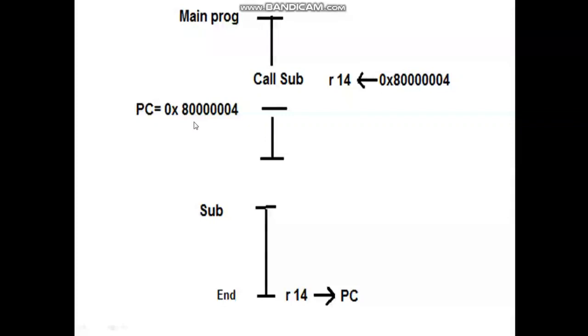You know, when an address is to be pushed on the stack, the stack is in the main memory of the system and it is outside the CPU. Therefore, while pushing the content of the program counter on the stack, the processor has to provide the address of the stack, then it has to generate control signals, and then this address will be saved in the external memory.